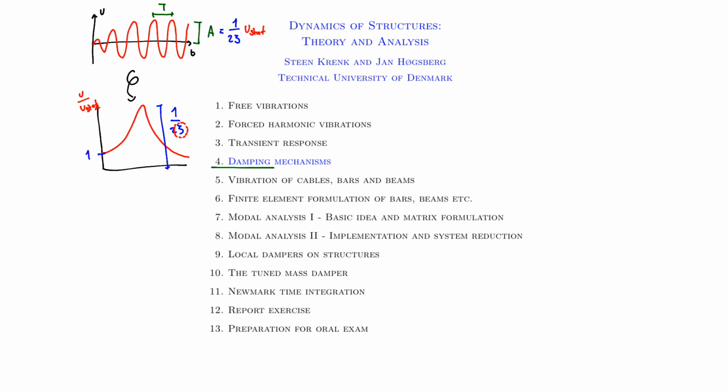So the damping ratio is crucial in estimating the amplitude of the structure and thereby determining fatigue or lifetime of a structure, the collapse analysis of structures. Many things are actually directly governed by the damping properties in a structure, and thereby it is highly critical that we have good damping models to be used in real life analysis. And that's a main drawback of today's state-of-the-art in dynamic analysis, and something I think we should improve.